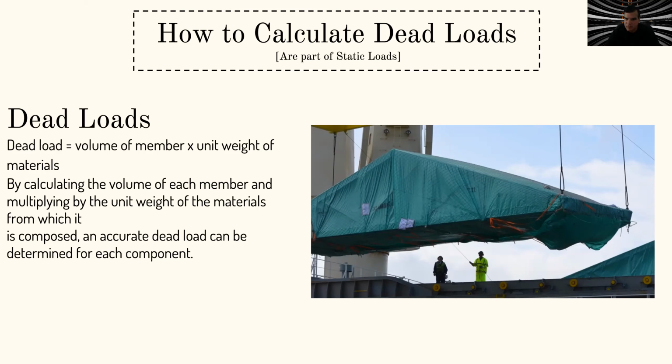It's a little bit boring to calculate the dead loads because you need to take every element of the building and give a weight. For example, wood has a specific weight according to the type of wood. Well, we will measure the dimensions of all the pieces of that particular wood that are located in a place.